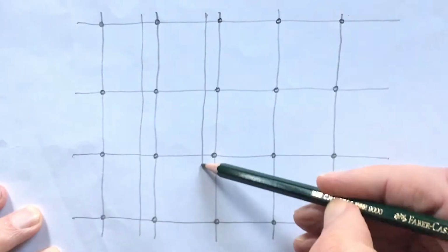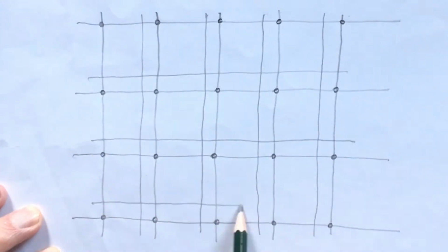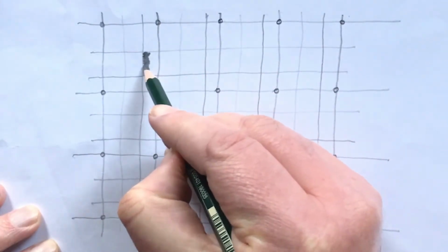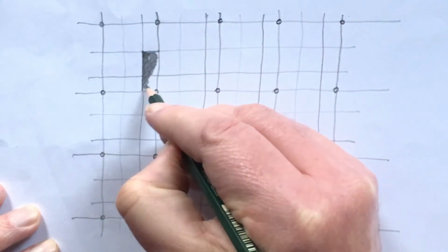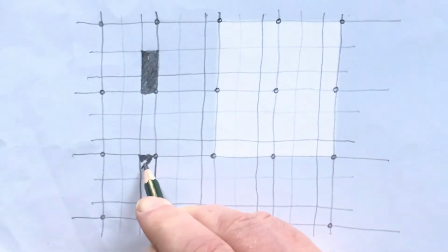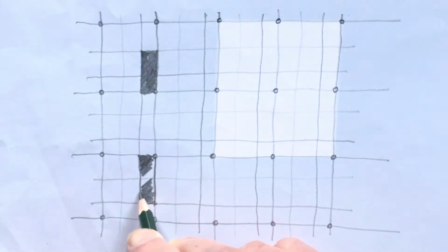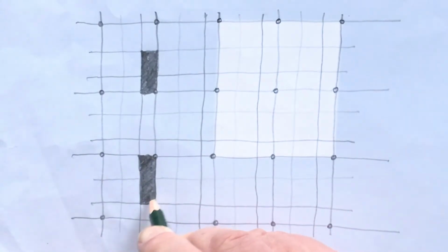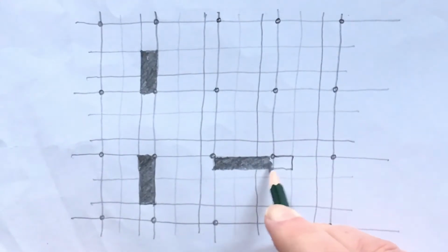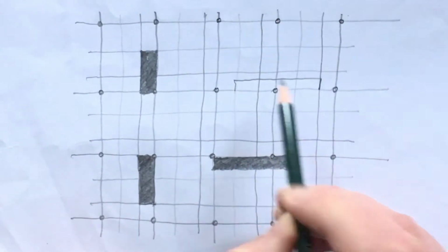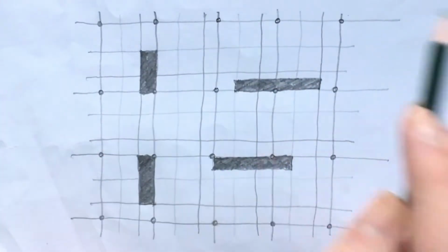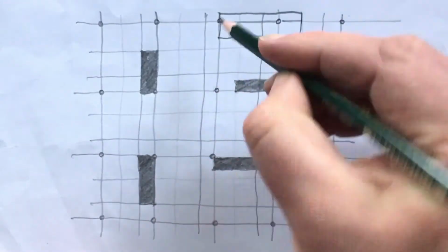If I draw a very basic tartan grid, we call this a tartan grid, we could decide that these smaller rectangles here, these are the places where I put my services or my less important spaces. And in the larger areas here, the squares and the big rectangles, well, this could be where I'd have living room spaces or library reading rooms or maybe double height spaces. And the way the grid works is once you propose it and put it on the page, something of your organizational principle is transferred to my imagination without you having to draw the entire building.